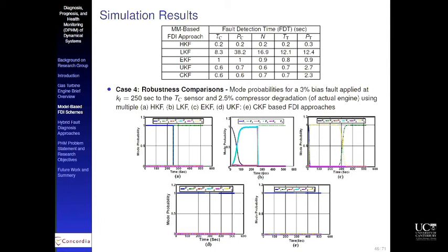On the other hand, if you simply use the linear Kalman filters, you see that even during the time when the system is healthy, your mode probability associated with the healthy mode starts to decrease. At some point, it's going to cross another mode probability, 4. So this is a misclassification. This is a false positive classification that your linear filtering is telling you.